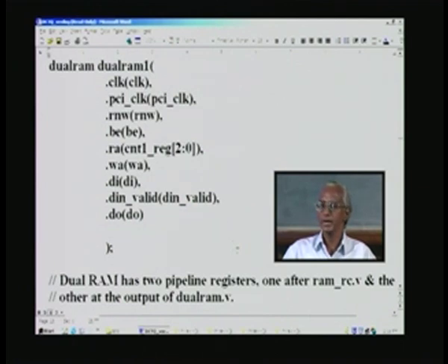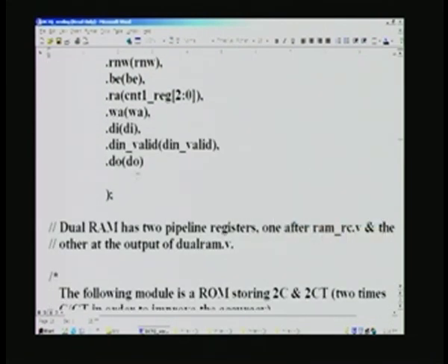because in the first computation of Cx we take a row of C and then take a column of the X matrix, and repeat the same for other columns of the X matrix. That means we advance to the next row of C only after processing 8 columns of X, and that is the reason why this is put as LSB, and the MSB of the counter, that is bits 3, 4 and 5, will be for the C matrix, which we will be seeing later on, and the final output is D naught here, and this is applied to the second stage, which we will be covering shortly.